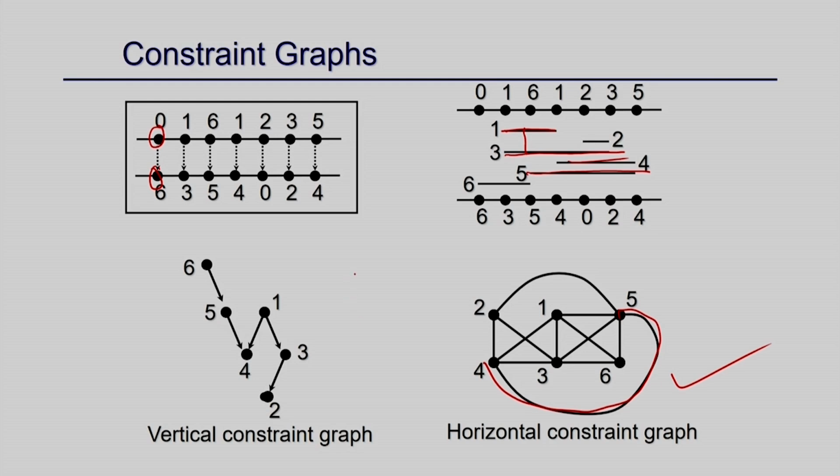What I am trying to say is that if there is a connection, say 1 to 3, then whatever the connection is happening, say 1 to 1, this 3 cannot go here, right. You cannot go across this. So, if this is the track, say 2, the connection from 3 has to happen below this; it cannot go crossing this, right. So, that is what is called a vertical constraint.